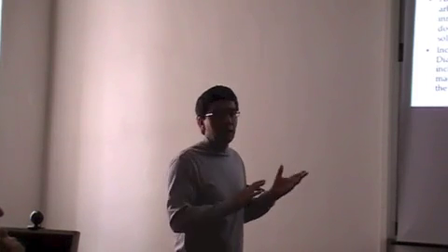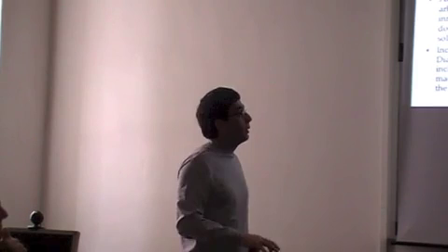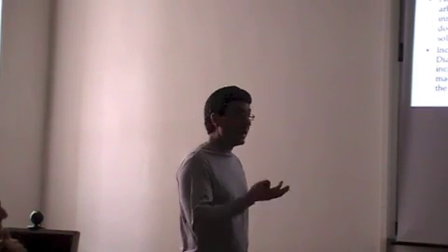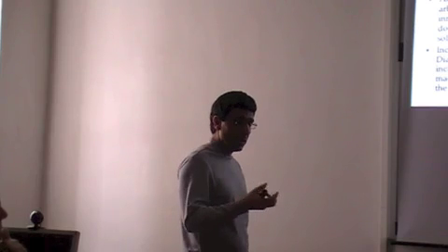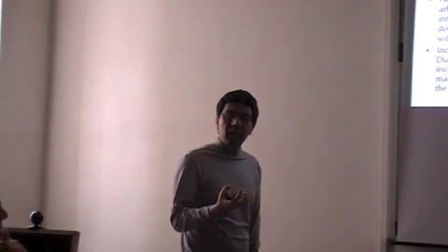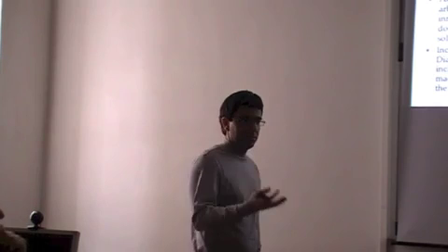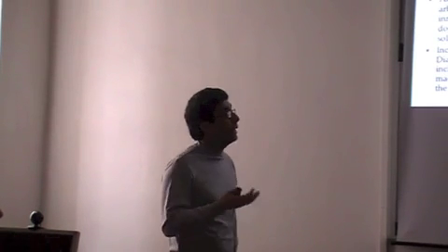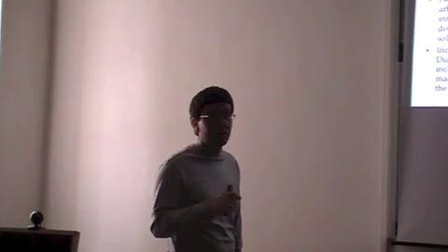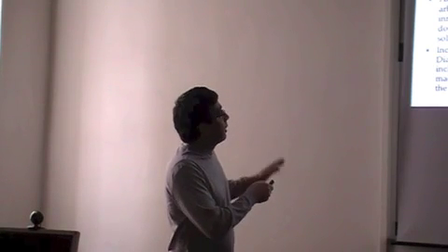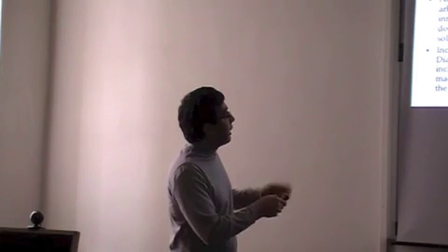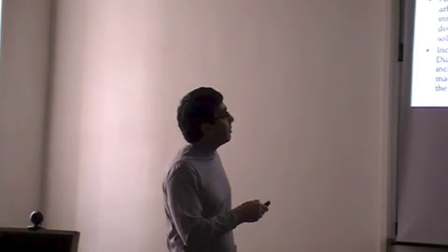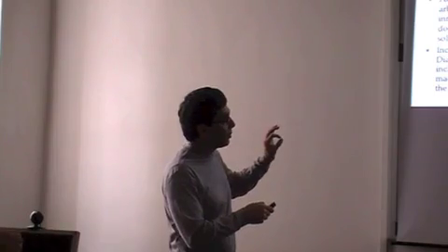I can look at that in the generality that Eshelby proved. I don't think that result holds in general, but I'm going to be looking at a spherical inclusion with some eigenstrains that respect the spherical symmetry. There have been some works to extend this to nonlinear elasticity, mostly for harmonic materials in 3D.